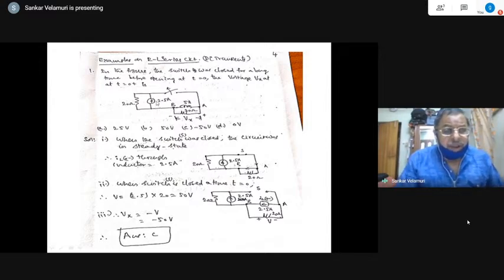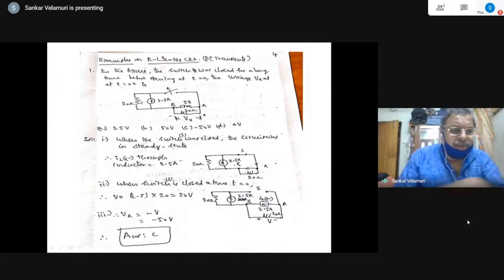In case of doubt, you convert this independent current source into a voltage source because it is a practical voltage source, right? So it is a DC transient. So it is equivalent to a simple RL combination with L and R prime being parallel in this particular branch, and this is a voltage source only, right? And a practical voltage source can be converted to a current source, or a practical current source to a voltage source. These are some of the key issues.